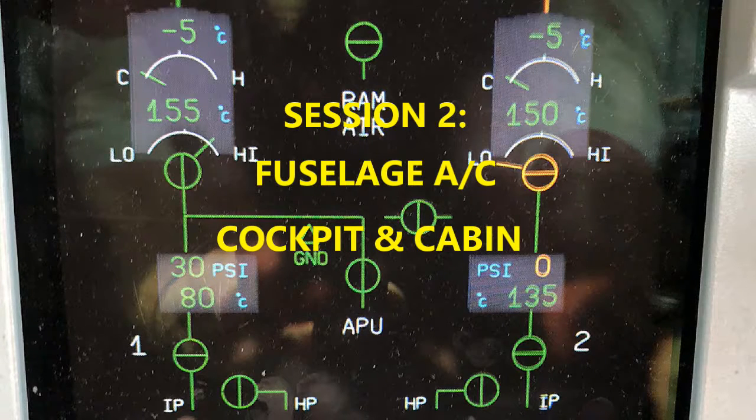Okay, so with the air conditioning packs, each of them has a computer. Those are your pack controllers, and the purpose of that is again to monitor the temperature as it's going to get distributed to the cabin. There are two computers like I mentioned before, and the pack controllers are installed at 95 VU and 96 VU. They're going to be calculating and sending those signals back to the zone controller.